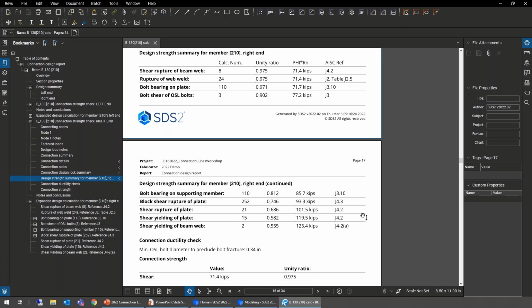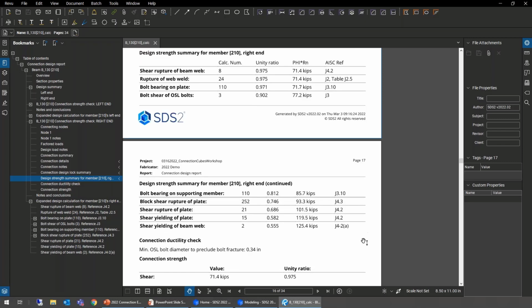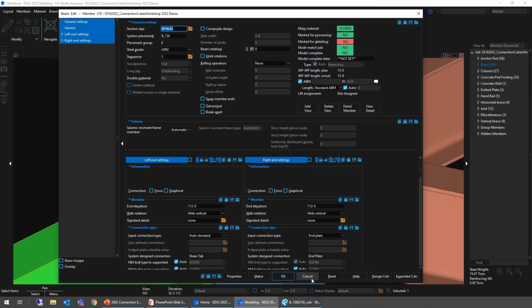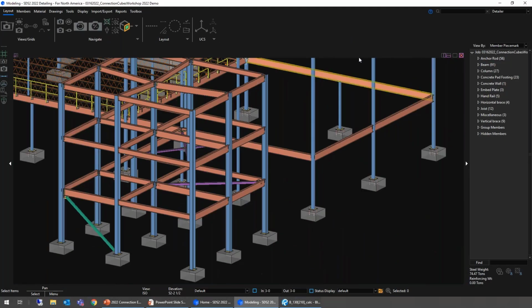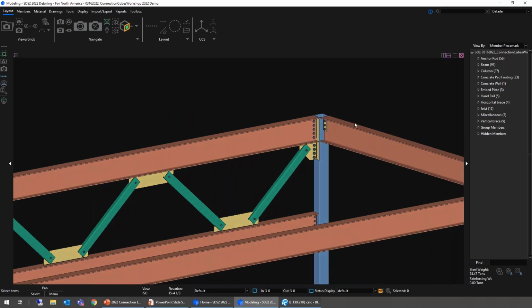Anything else you want to point out in here, Colin, that you feel might be important that we've changed or updated? One important thing I forgot to mention as a part of this project is when we have interaction of loads on connections. For example, an axial loaded beam connection, we now will call out the limit states that have that interaction with an asterisk near the capacity. We wanted to do that just to make it clear which limit states included that interaction, and because feedback told us that that sometimes was misunderstood. So we wanted to show that more clearly.